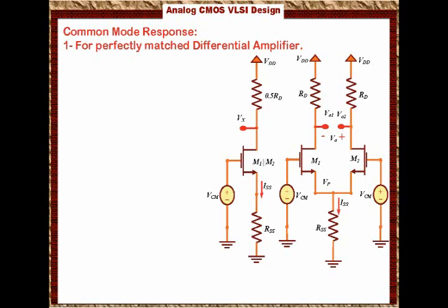So basically what we're saying is, when it comes to the common mode voltage, we are stressing the common mode input voltage. This amplifier has one equivalent half circuit, and the two transistors will behave in parallel, and this will be the equivalent circuit. So this particular circuit is nothing but an amplifier.